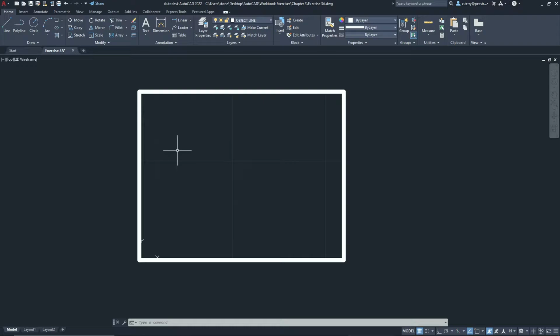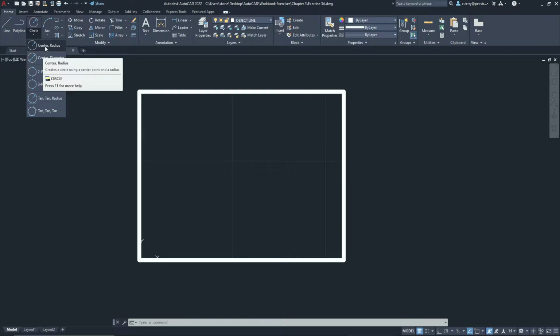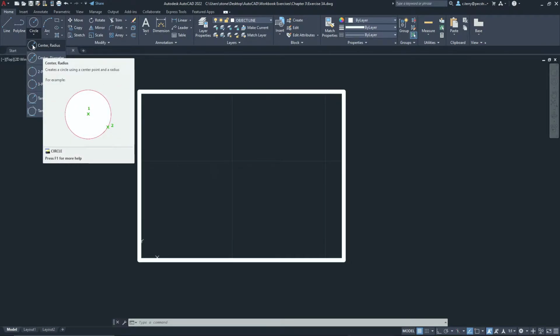All right, circles. If you go to sheet 3-2, it talks about circles and all the different ones that you can do. I'm going to show you quickly over here. If you drop this down, you do have 1, 2, 3, 4, 5, 6. They're basically broken up into 3 categories, to where when you draw the circle, you can specify the radius, and it shows you right here what the radius is.